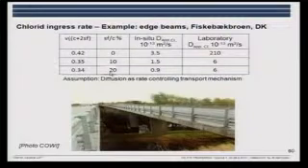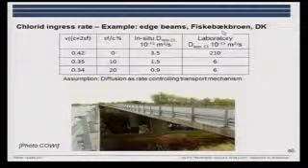It's relevant because when you have concrete with low water cement ratio and silica fume, it may not be that easy to work with and we may have the risk of autogenous deformation. So if you're just choosing your mix based on these lab tests, you may end up with something which is not that easy to work with, and you may create other problems. So that's why we actually started looking at this.